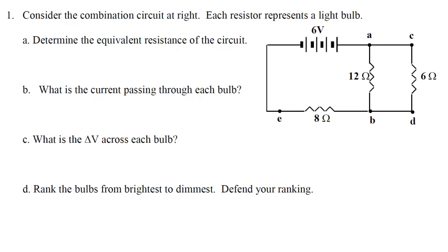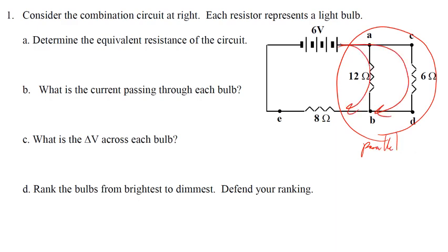So what we have right now is we want to find out the currents and the voltages going across the different resistors that we have. What we see is that we have two parallel circuits here. We know that because the current can go through one or the other. However, because the currents come together and have to go through the 8 ohm resistor, we know that one's in series. So the series resistor is connected to the parallel ones.